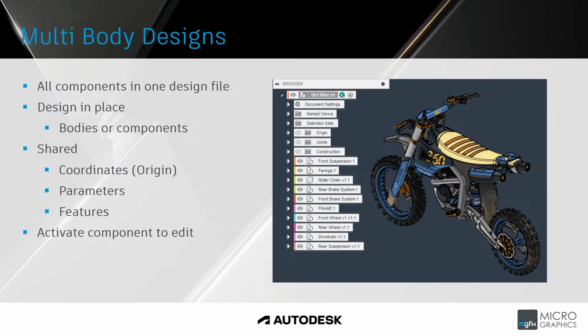All of these parts are designed in place, and what this means is that they share a few things. They share the same coordinate system. They will all have the same origin. So if you look at the front wheel and the back wheel, they would typically share an origin point. When assembling these together, if we pulled out these components and created a different assembly, they would all line up to that same origin.